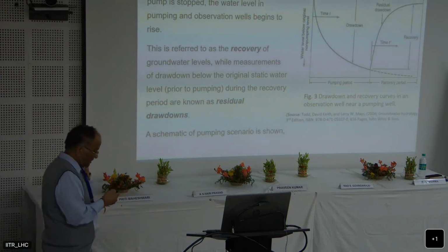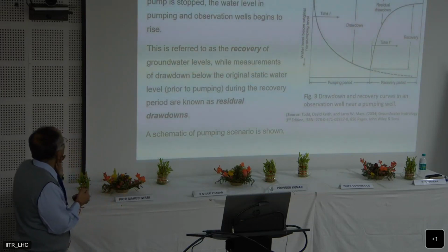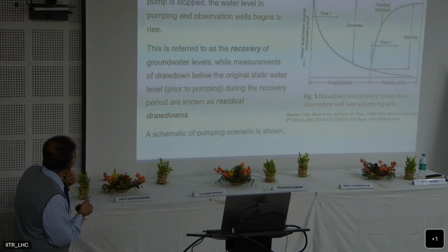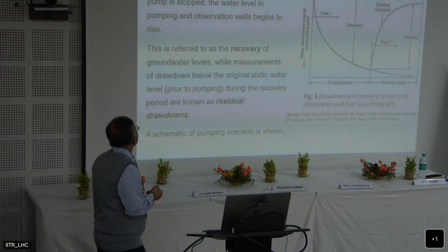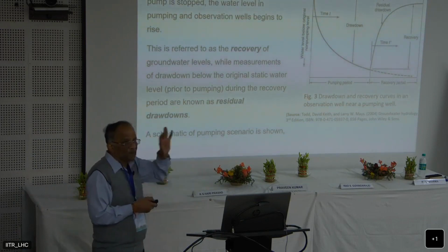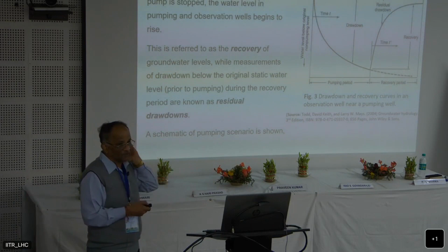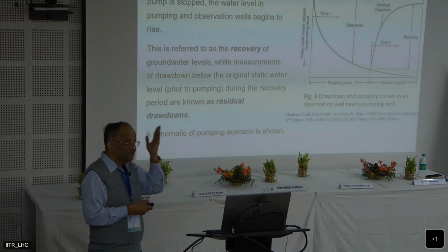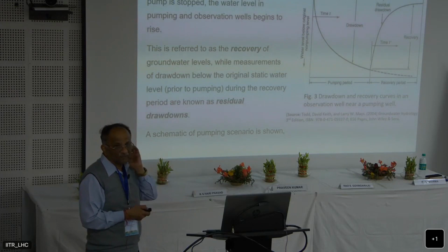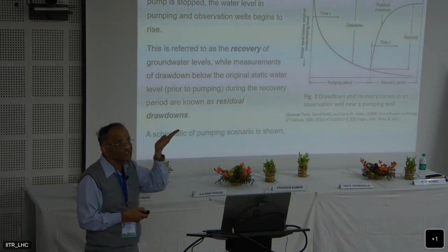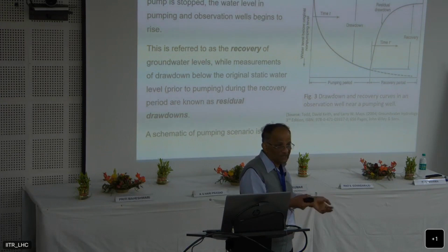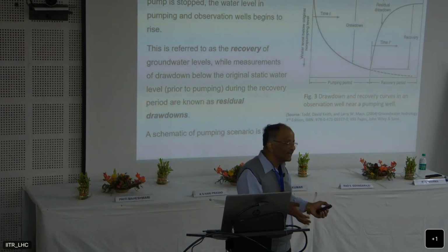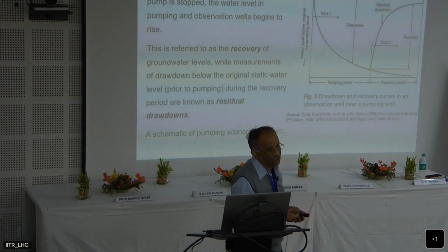One more important test which we do for pumping test analysis is the recovery test. In a typical recovery test, we pump the water for some time and then we stop pumping. Then we record how much time it takes to recover, that means for the water table or the piezometric surface to come to its original level. Let us say I pump it for 5 days and stop pumping. Do you think another 5 days will it take to recover, or will it take less time?